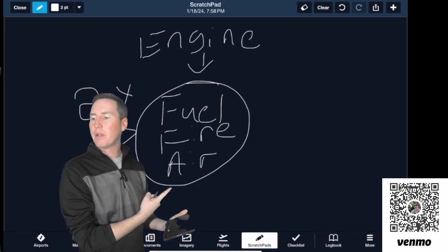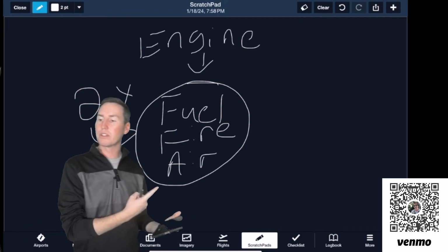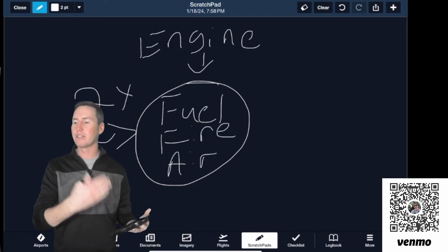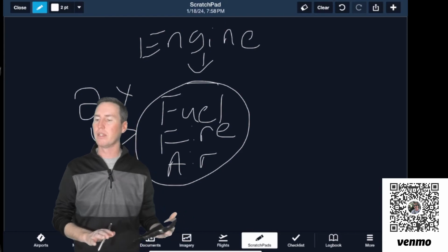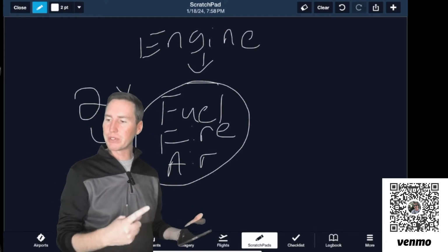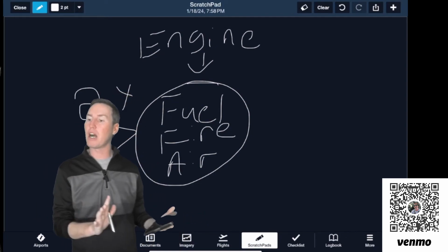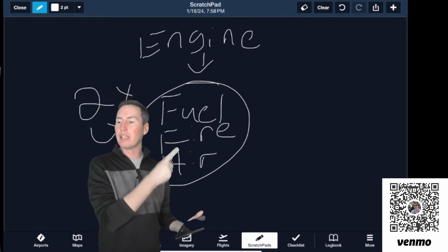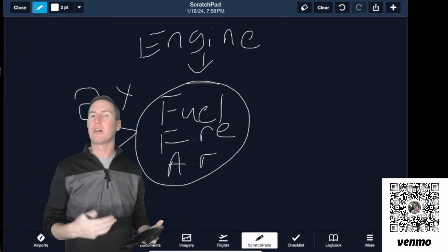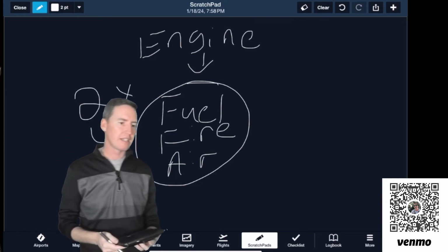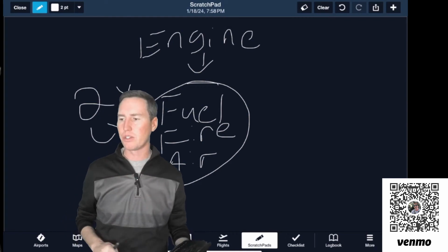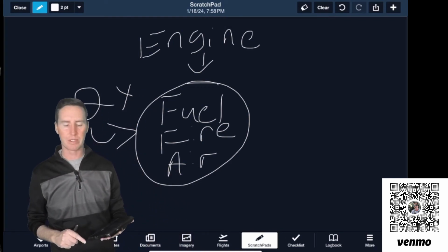And then air, how we get an alternate air. Our primary air source is through the front of the carburetor air box, and that is on the front of the engine, just below the prop. And it has a filter there, so we're checking that on pre-flight. If that was to get blocked, then another way to get air to the engine is by pulling carburetor heat. And then we talked about what carburetor heat does. Basically, below 2,000 RPMs, we pull it. But again, look at your AFM, and it will tell you when to do that.